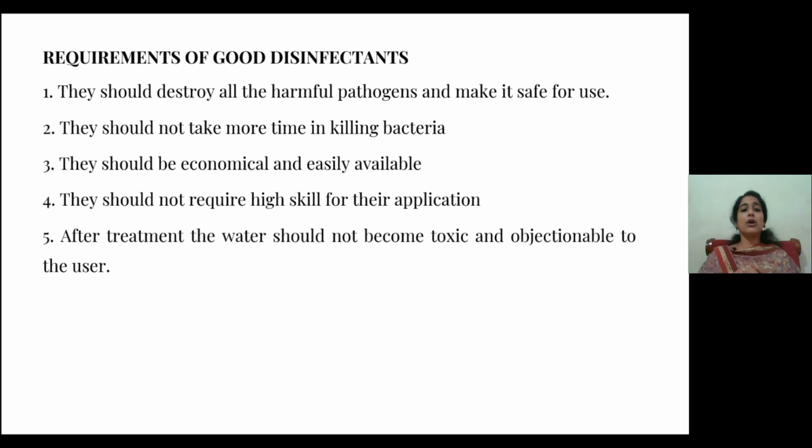They should not require high skill for their application. After treatment, the water should not become toxic or objectionable to the user, that is, if there is a smell or any other difficulty related to the disinfectant. Basically, disinfectants are chemicals, and if these chemicals cause any of these difficulties, we cannot use that disinfectant for our water treatment system.